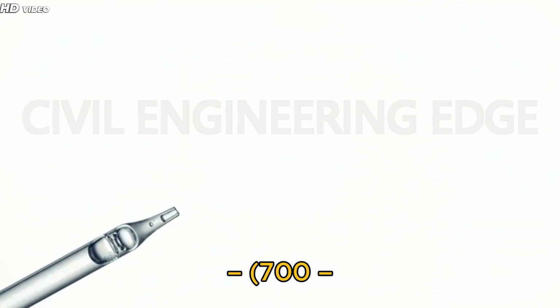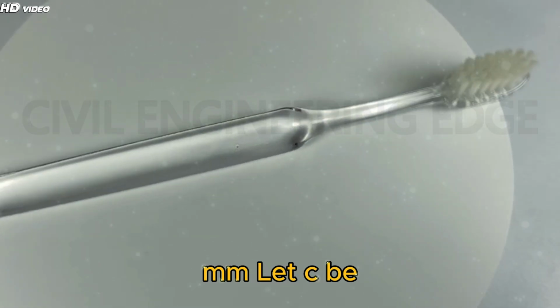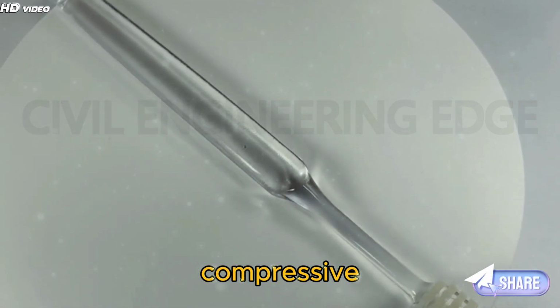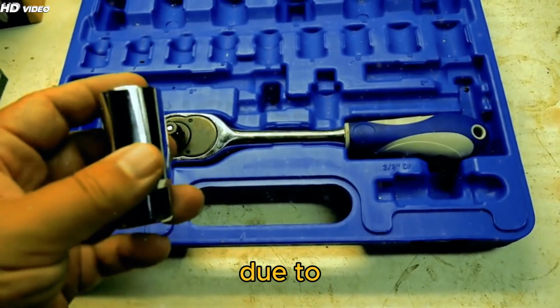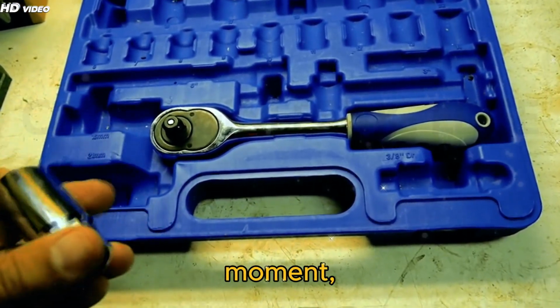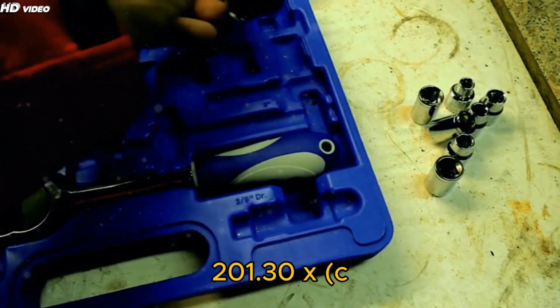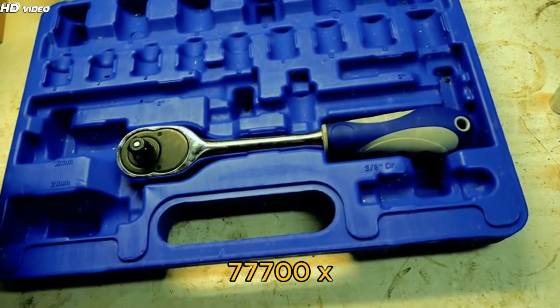Lever arm, alpha, equals 650 minus 201.30 / 3 equals 582.90 millimeters. Eccentricity equals 1610 minus 700 / 2 plus 201.30 / 3 equals 1,111.30 millimeters. Let C be the compressive stress in concrete due to bending moment.